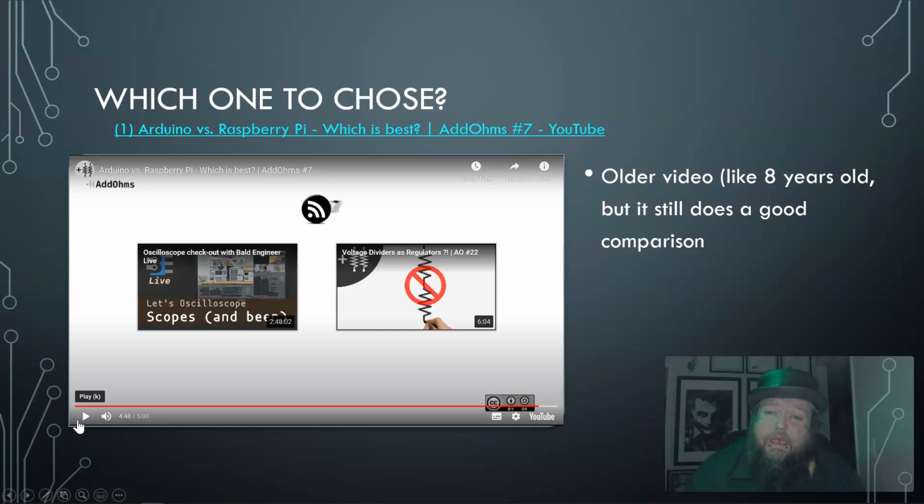When they said that, you should have picked up on what it said for the power, for what it can actually run. That it said that it had like 40 milliamps versus 5 to 10 milliamps. And now remember, amps are the measurement of current, of what can flow, and enough current to be able to run stuff off of that. That 40 versus 5 to 10 is huge and different. So maybe the Raspberry Pi itself in that example would have to have more power sources.